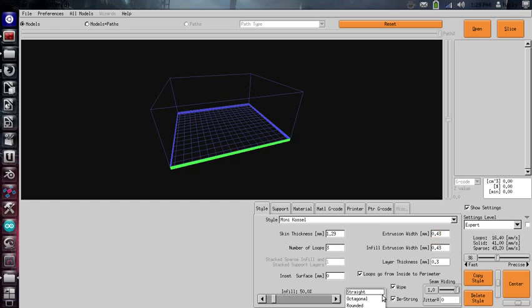Infill style, this is going to change the pattern by which you do infill. Infill percentage, this is going to change the percentage of infill. It's pretty self-explanatory. However, I will give you some rules of thumb. For parts that are not structural, that are made to be pretty, 20% is a good number. Unless it's an overly complex model with lots of small fill areas, and in that case, you would want to set it to a higher value. Somewhere around 33% for a pretty model would be a good number. Now, if it's a structural model, you're going to want to set it to 50%. This will give it added structural stability. And also, a note, 100% is not a good idea.